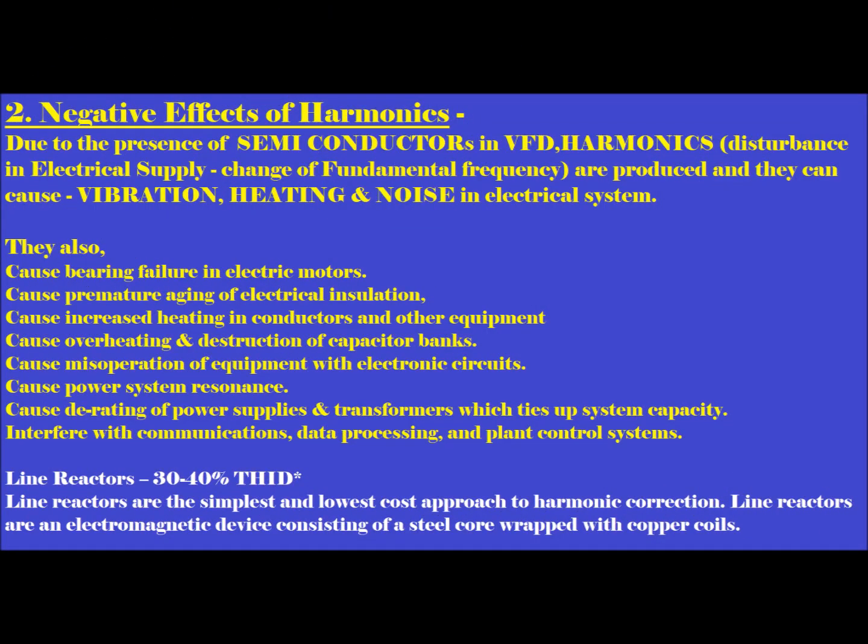We'll come to the second point, that is the negative effect of harmonics. As we know, drives are made up of semiconductors. Due to the presence of these semiconductors in drives, harmonics are produced. So what are harmonics? We can understand it as basically a disturbance in the electrical supply, that is a change of the fundamental frequency. The fundamental frequency here in India is 50 Hz, but due to the use of semiconductors, the frequency gets disturbed, and because of that disturbance, or the creation of harmonics, they will cause vibration, heating effect, and noise in the entire electrical system associated with that drive application.